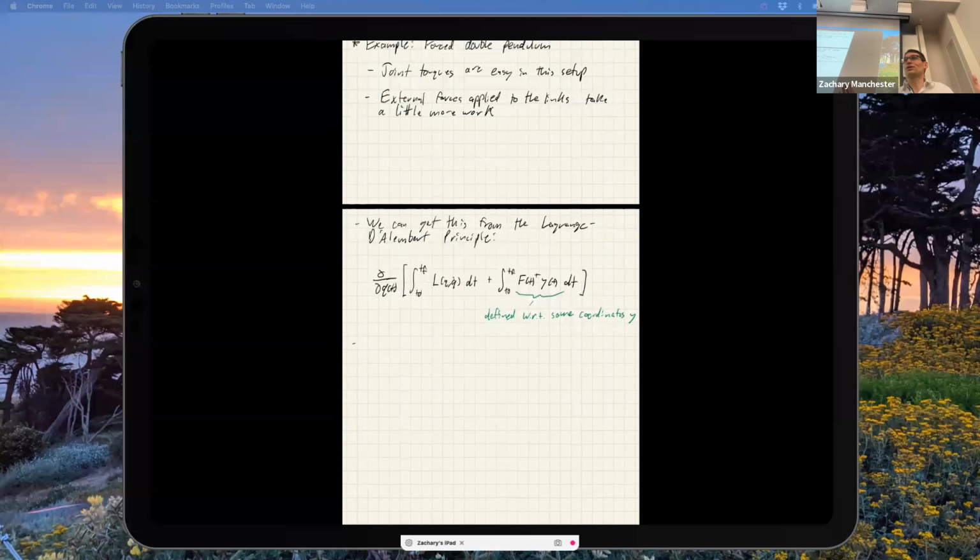And then that's it. That's all you've got to do. Whatever's left multiplying the delta q is the forcing term on the right-hand side. And all I did was pick up a new Jacobian that maps those forces. So that's how you get that end effector Jacobian that shows up to map end effector forces into joint space.